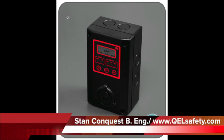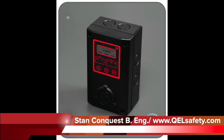Just wanted to mention with the Q5 also, you have several options on the display. It will show CO, the concentration, or any gas concentration. You can also choose the screen to just have CO normal. In some locations, if people see any type of reading, they may panic and say, okay, there's CO here, we better evacuate the room. So you have that user selectable screen.